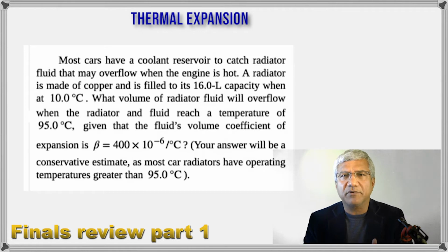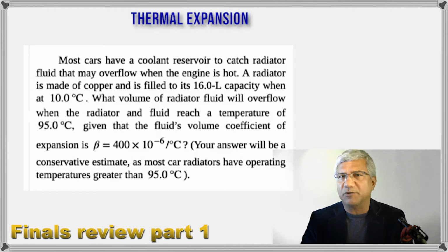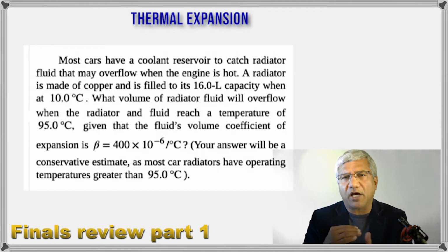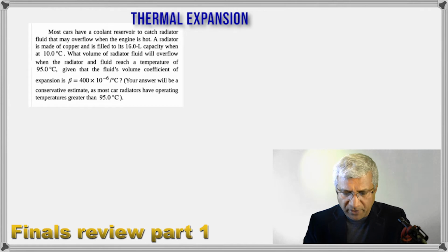If, for example, both are expanded equally, which is not going to happen, then nothing will overflow. Because if the radiator expands by an equal amount as the fluid, then nothing overflows. But fluids always expand more than solids. So the fluid is going to expand more, the radiator just a little bit. So to find how much overflows, we will take the difference. That is the idea here. So that's what we're going to do.